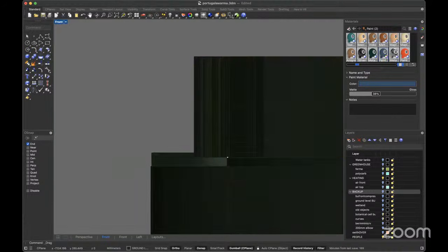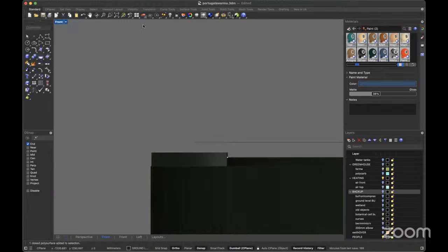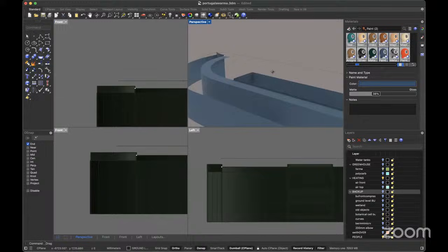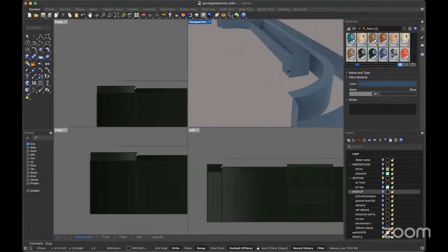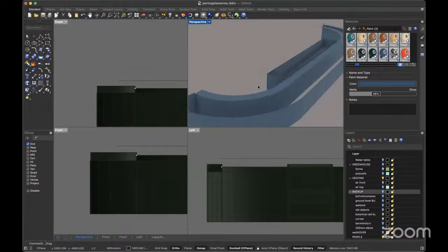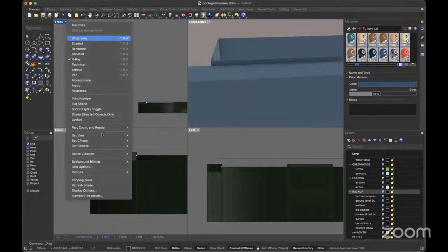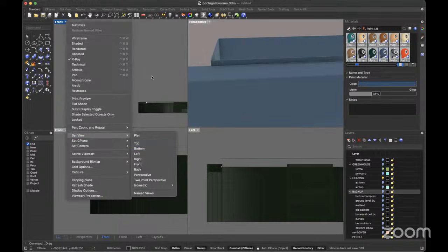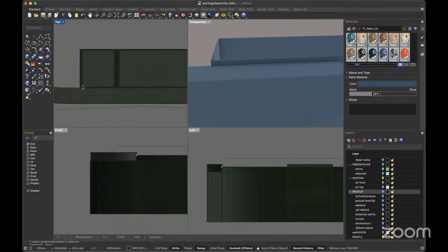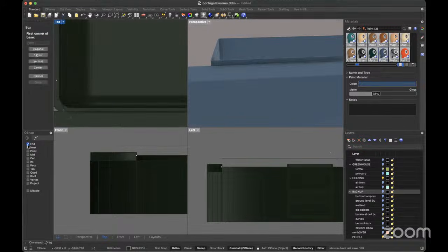Okay, now again, I'm going to take a solid difference from that with that. Let's look what we've done. Yeah, it removed. And obviously now this also needs to be, set view top. Need to remove this ridge. So I'm gonna draw a little box here. I can snap to near,